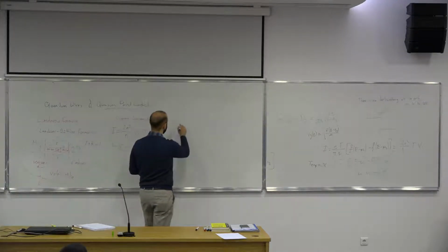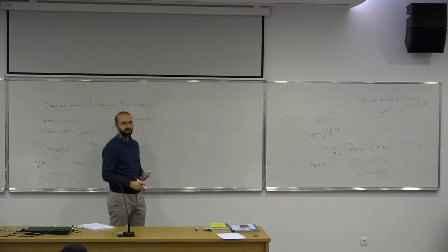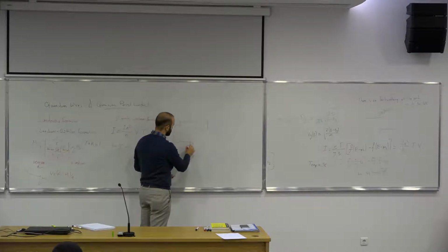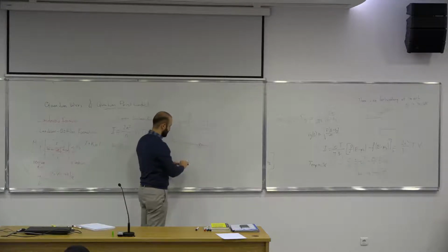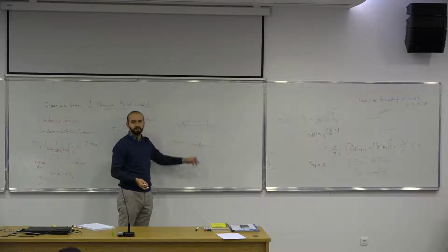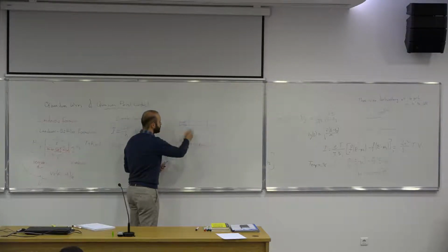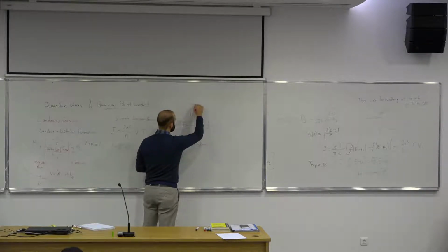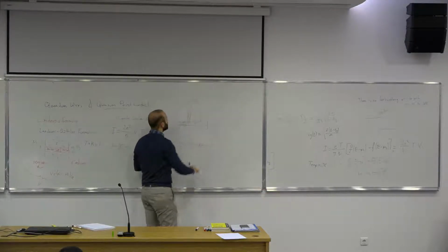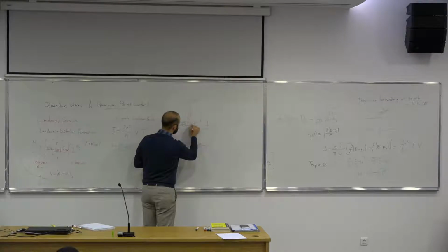What I mean by 4 probes, what we typically do is this. This can be applied to any measurement. Let's say you want to measure the resistance of this object. We apply a certain current through these terminals, so a current flows through the device. You can apply a voltage and measure current, or if you have a current source, you can apply current, but it doesn't matter. What matters is we send a current with a known value through these 2 leads, and then with another pair of leads, like the ones we use in the quantum Hall effect, or Hall effect simply, we measure the voltage drop across this region.